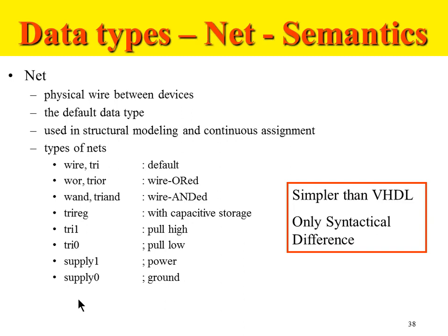If you remember, we saw that only some subsections of Verilog are synthesizable. That means I can convert that Verilog to a working FPGA or a working ASIC in hardware. The other part is only meant for simulation or testing purposes. Wire and tri are meant for design purposes, for implementation. The rest of the stuff is only meant for specific testing purposes, not to be implemented on the FPGA.